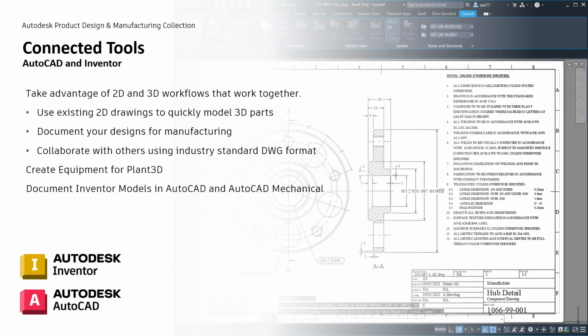Let's start with digging more into AutoCAD and Inventor. With AutoCAD, you can actually take advantage of 2D and 3D workflows together. You can use existing 2D drawings to bring those into Inventor and create 3D parts from them. Basically putting your 2D AutoCAD drawing on two different planes and then creating extrusions from that geometry. There are some nice tools in there that can link that to existing AutoCAD geometry. If it were to change, they can update your Inventor model. There's some neat stuff there.